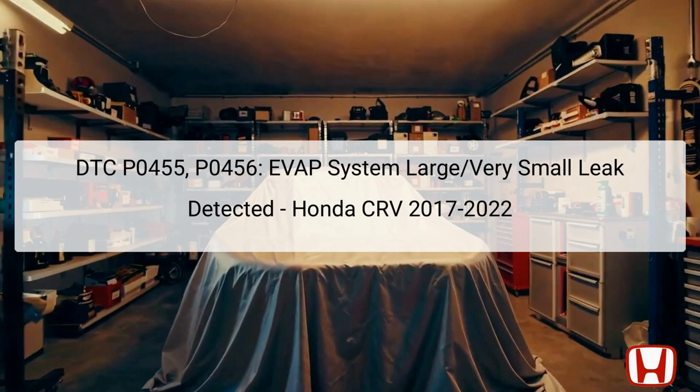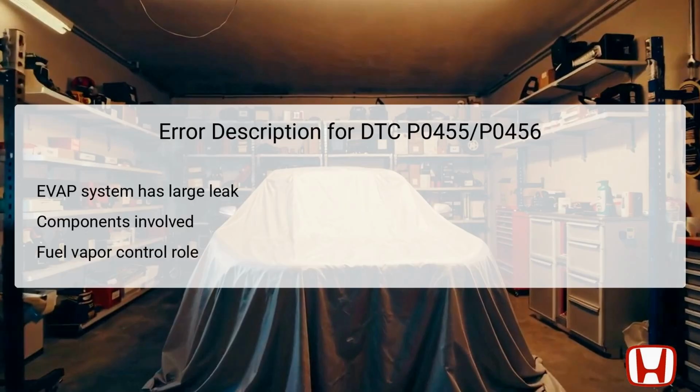necessary for these DTCs. The EVAP system in the Honda CRV captures fuel vapors from the fuel tank, preventing them from escaping into the atmosphere. The affected components include the EVAP canister purge valve, EVAP canister vent shut valve, and the fuel tank vapor recirculation tube. The EVAP canister stores fuel vapors until they can be purged into the engine for combustion, aiding in fuel efficiency and emissions control. The location of the EVAP system components is primarily in the engine compartment and around the fuel tank, making accessibility essential for effective troubleshooting.